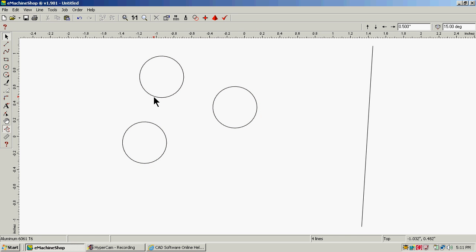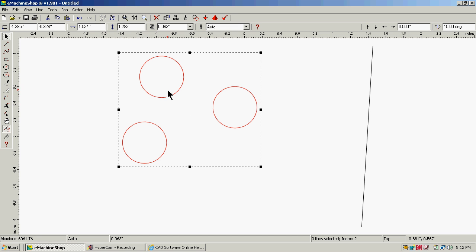Then I select one, it's going to select them all. And then I right-click on one of them and say Copy. Now, before I click Paste, if I don't want it to paste right on top of the drawing that I have there, especially if I forgot to group it first, because if you try to take the parts that you just copied back off of it, you only get one or two pieces one piece at a time. So you want to group it first, then move it.